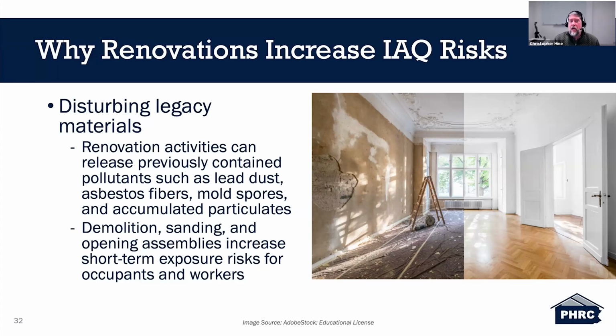Looking at asbestos, right? I'm sure many of us have walked on tile floors that were asbestos tile, right? And we weren't worried about that because the asbestos was confined, it wasn't being disturbed. Those of us who have been in older buildings that have steam pipes, oftentimes those steam pipes were wrapped in asbestos insulation, which again, we weren't worried about until it was disturbed. If we're doing remodeling in an older unit, right? Disturbing this material, it could be asbestos. And now we have some potentially some short-term exposure risks to the workers and the occupants.